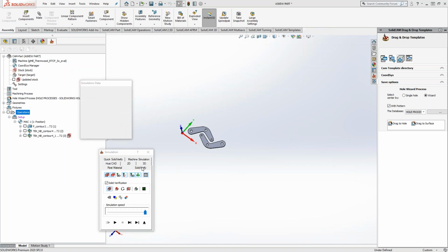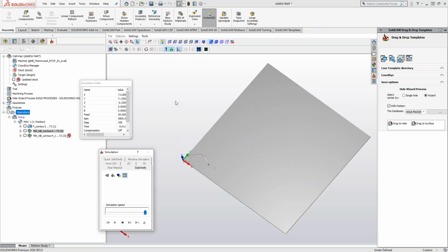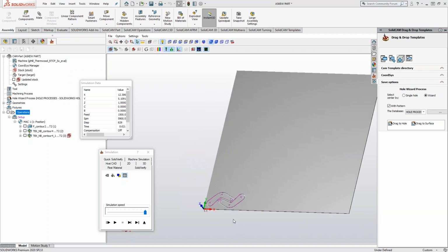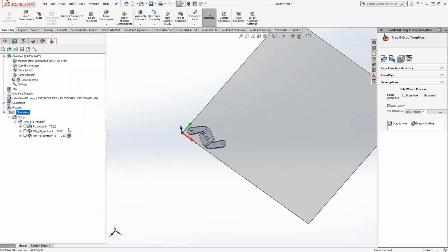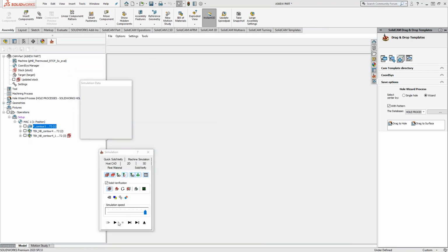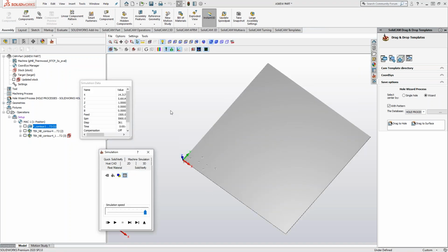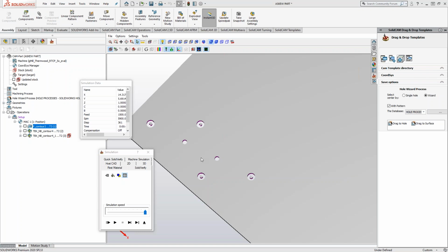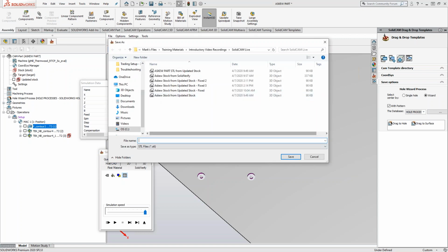If you wanted to just output or save out that STL file in a certain spot, like if Mark just wanted to do that contour 2 and then save that STL file out with just that contour 2 toolpath in there, he can do that as well. Yep. So like Kevin's just saying, I just did that one toolpath. It's just doing those holes there. We can go to File, Save Machine Stock to STL, and then it basically just asks me to give it a name.